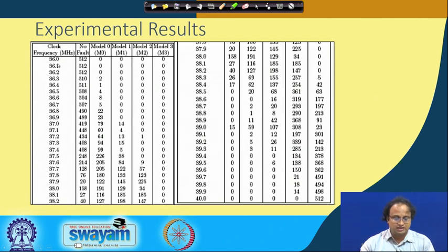So again, if you remember, this is my basic setup, and imagine that the AES operates at 36 megahertz. What we do is we tried 512 fault injections using the clock generator. Why 512? Because that is the limit of the embedded logic analyzer. We then take a statistical analysis of how the faults distribute across the models M0, M1, M2 and M3.